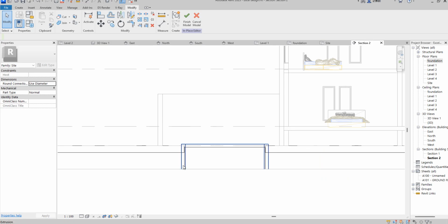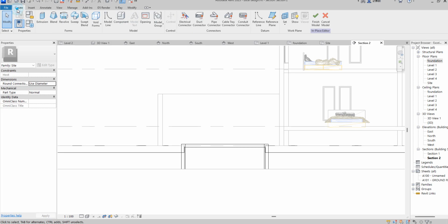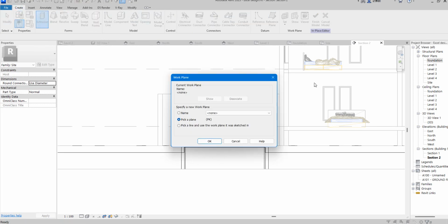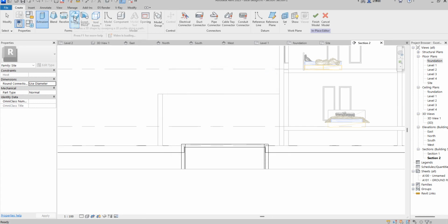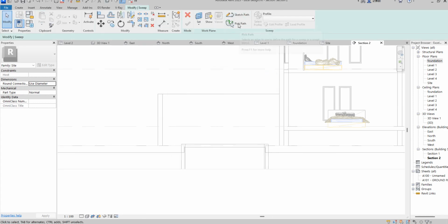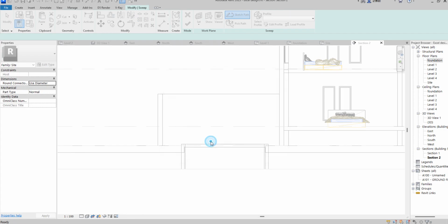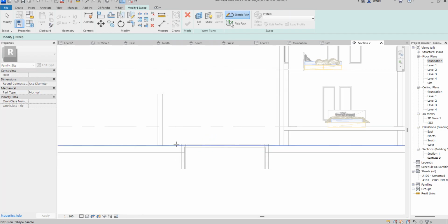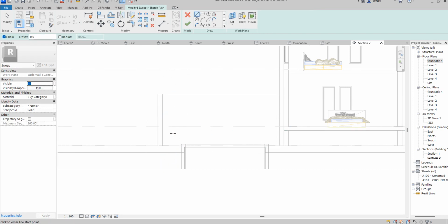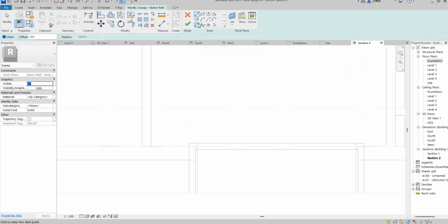Now I want to create the iron that we're going to put inside. So I will say extrusion, no, not extrusion this time around. I'm using sweep to work on that. So sweep, pick, telling me to pick parts. You can decide to pick or use surface, whatever you feel like using. Let me just use this one because this one is available for me. Based on align to that, I will adjust it later and bring it in.